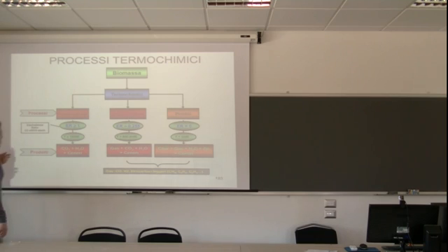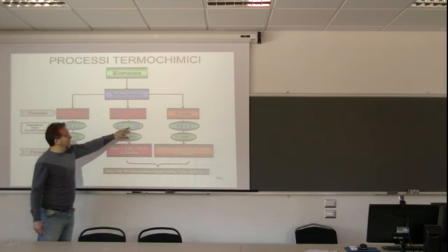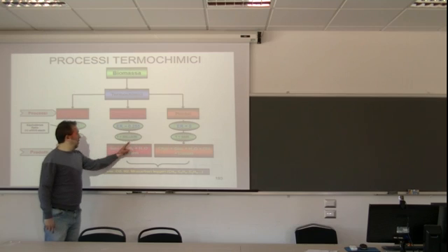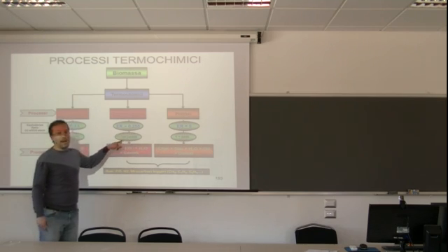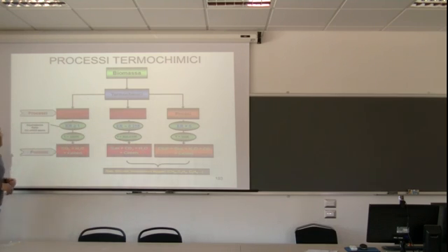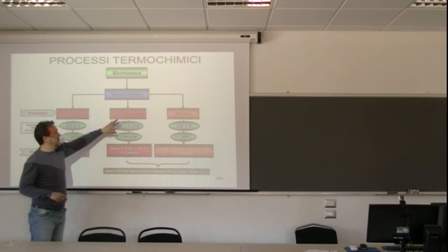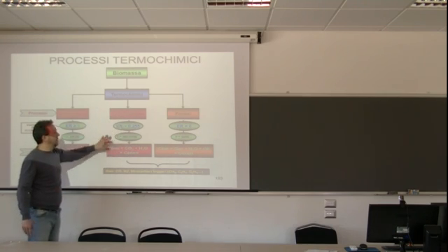There is a very particular value which is around 0.25 of equivalence ratio. So it means that you give only 25% of the oxygen needed for the complete combustion. And it means that you have a lower temperature, because the combustion is lower, and you obtain some energy that the system needs for maintaining the process.